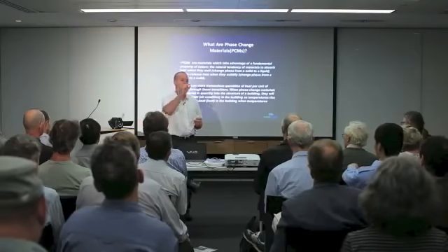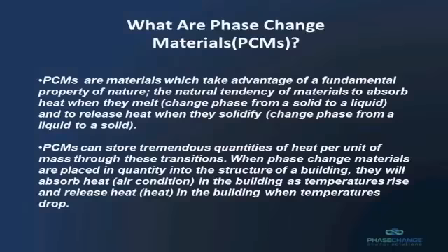Who can think of another phase change that happens almost every day in our work environment? Anybody? Air conditioning. The liquid that goes through the coils in the air conditioner evaporates into a gas, which is a phase change. And then we take it outside and we squash it back into a liquid again and release the heat outside. If you take a pot of water and boil it on the stove, it hits 100 degrees, it doesn't get hotter, does it? So it's absorbing heat without getting hot. It's another phase change from a liquid to a gas. So phase change is not a new idea.